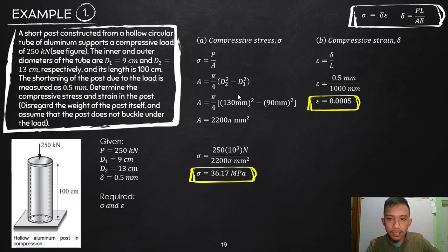I did not include here the sign, but in case you have a mixture of axial and compression, it is better for you to include the sign convention, wherein the compression is negative and the tension is positive, together with the strain, wherein the compressive strain is negative because that is shortening, and the tensile strain is positive since that is elongation. If there is a combination of that, so that you can differentiate, okay, if you combine these two. But since this is just a compressive, then actually I can just consider that as positive. But I need to bear in mind that that is compression, okay.